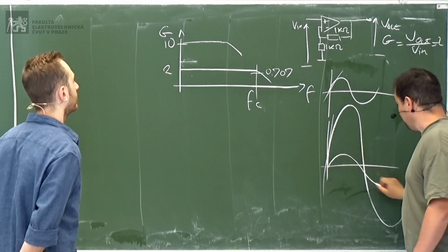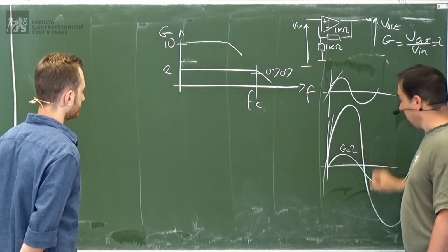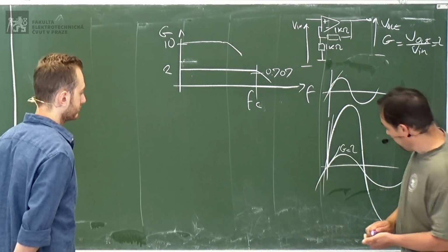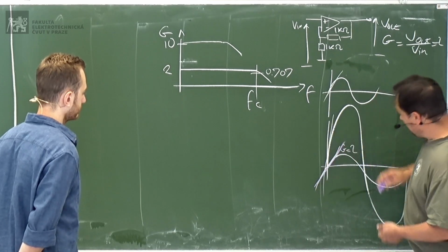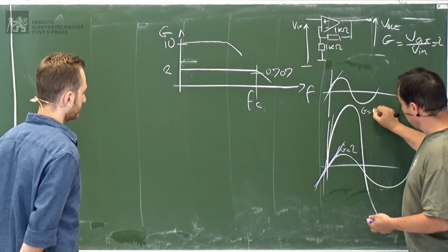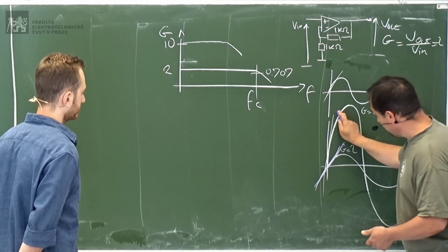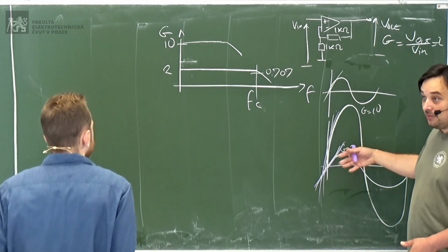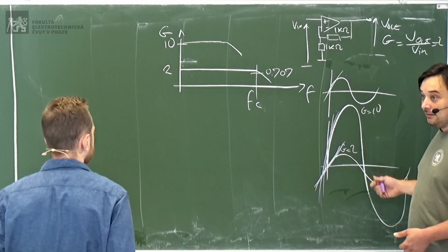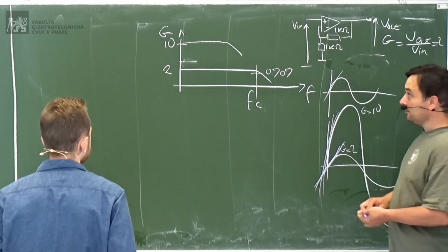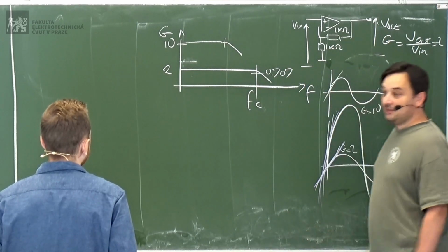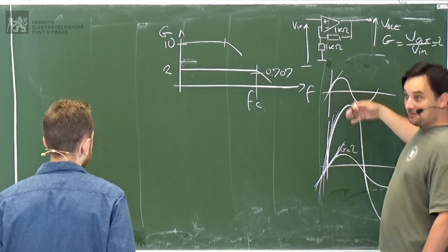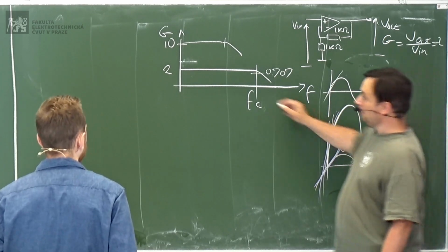If you have a gain of 2, you have this slope. If you have a gain of 10, the voltage will be larger, so the slope will be larger, okay? So you arrive at the point where you cannot keep up at a lower frequency. You understand? So here, boom, I've already started going down because I need a faster response to amplify bigger, okay?